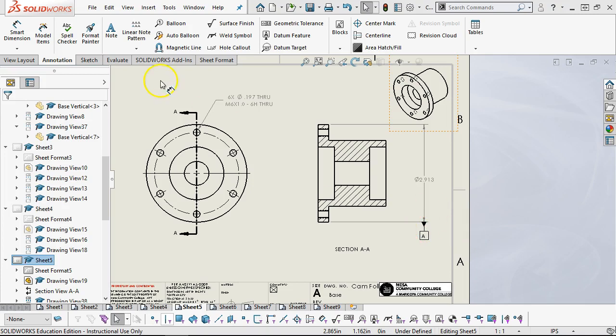So this is one I didn't think that far ahead. So let's go back in the annotation. We'll pick up a hole call out, 250 through. You know, the designation would, if it was just through the first, it would be near wall. We could put a note, add to the note through both or through all, or just the designation of 2 times. All right, because it's a disjointed or not continuous feature, then we'll want to take at least that much into consideration.